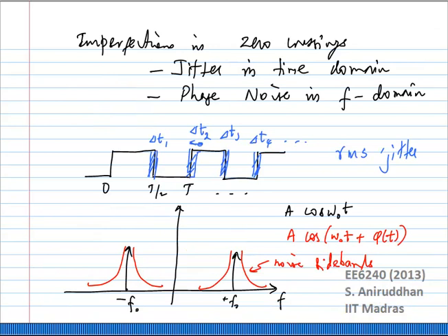Then we moved on to another very important aspect of the oscillator, which is phase noise, right? The reason we progressed in this manner is because we said for the same current you get twice the amplitude for the complementary oscillator. But why are we worried about amplitude? Because really in the mixer you want a specific amplitude, but if you want, let's say, 1 volt peak to peak at the mixer, the VCO can still generate maybe 500 millivolts and you can just gain it up, right? That's really just a matter of giving more current. So what is the significance of getting more amplitude?